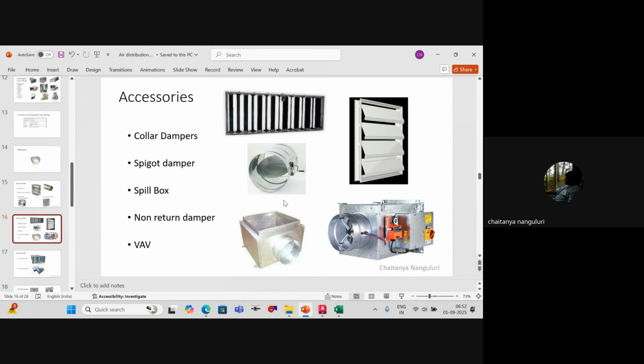Like a fire damper with actuator only, it will also be. In a fire damper, what will happen? Whenever there is no fire, it will be open. In this case, whenever the system is on, it will be open, else it will be in off state, to remove the complications. Understood? So, I personally don't prefer gravity type because the gravity type will have rattling noise.